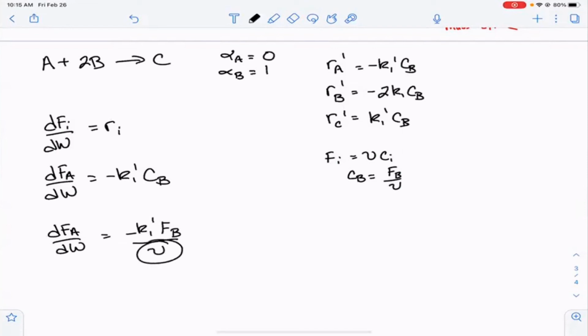So the volumetric flow rate is going to change as we go down the reactor. And again, that's another thing that we talked about. We did a derivation with respect to overall flow rates, but then we simplified that in terms of conversion. So I want to solve this without going to conversion. So now we're going to revisit that and get an expression for the volumetric flow rate as a function of the molar flow rates of each of the species.